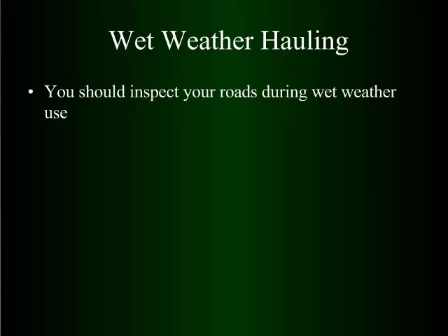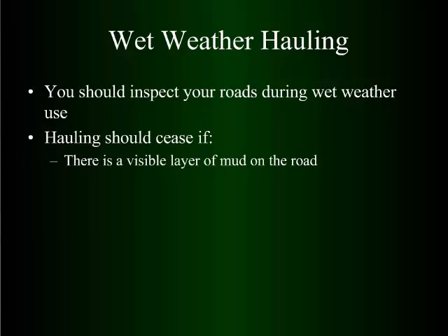Inspect your roads during wet weather use. Avoid them during wet weather. Don't use them during wet weather if you can, and obviously avoiding the spring breakup. You start seeing that layer of mud. You're pumping subgrade up through your rock, and your subgrade's your foundation for the road. You start failing the subgrade, you can have a total road failure. So you start to see surface deflection. It's time to take some sort of action. If nothing else, just shut off the hauling.